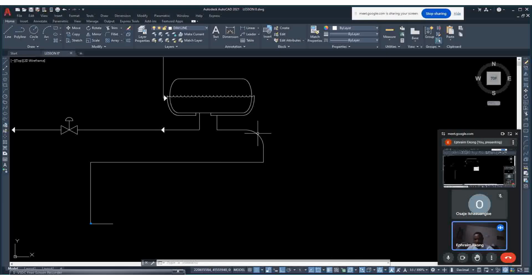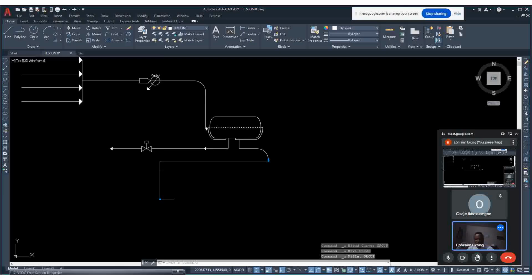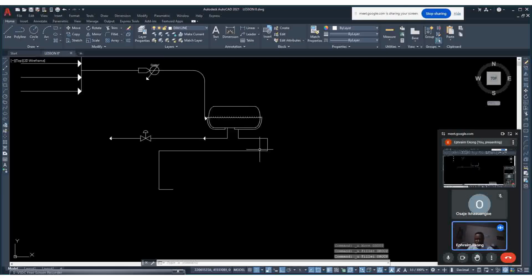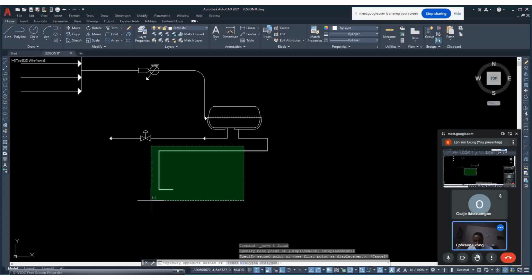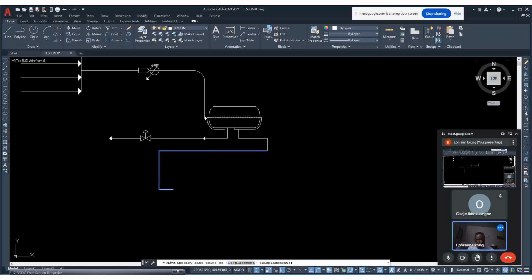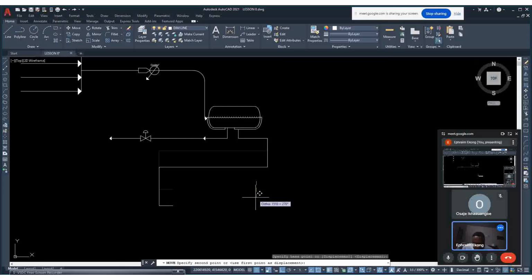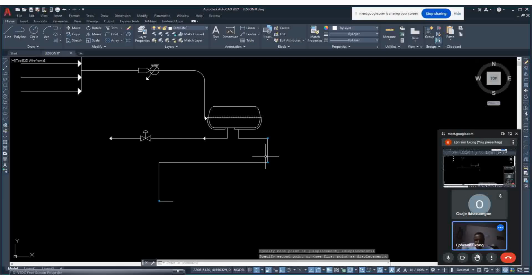All right. Let's undo. Okay. So let's align this line and move it downward a little bit. Click and so we align. Go to move. Click at this point, then take your mouse downward a little bit. I think this is okay. And you click. Okay. So go to fillets. Click on fillets. Click at this edge and click at this edge. Okay.